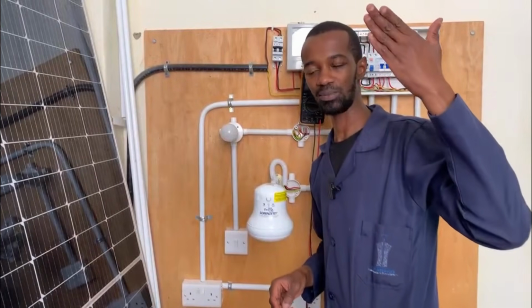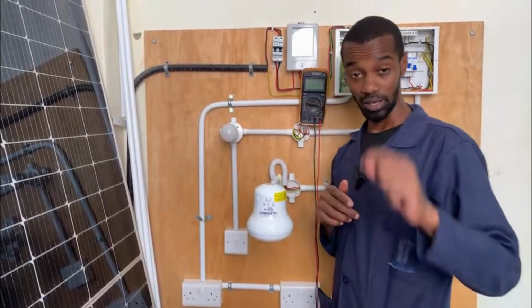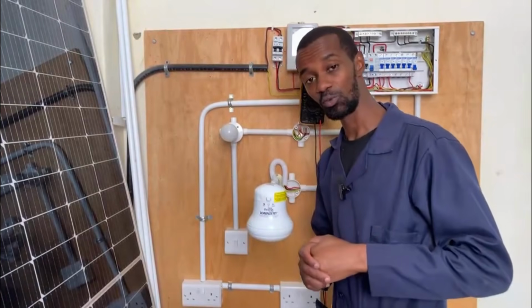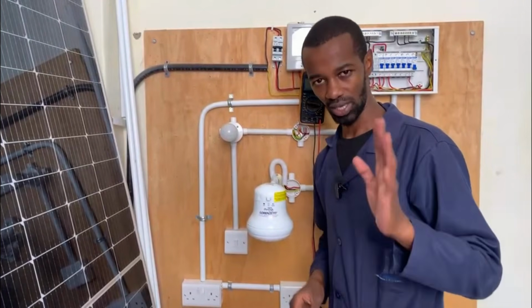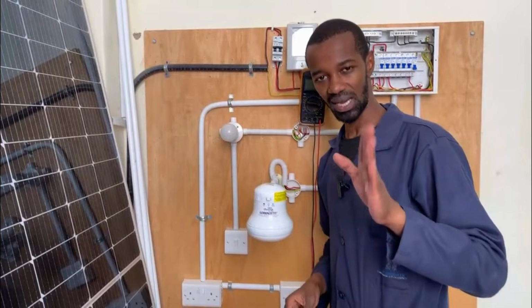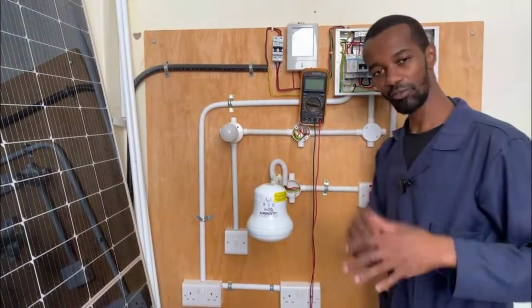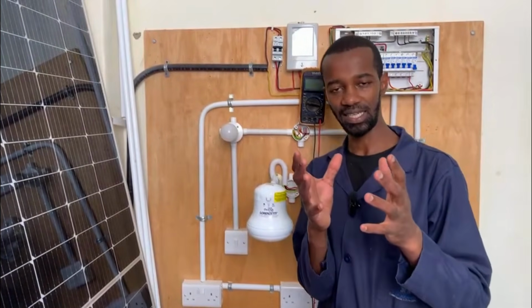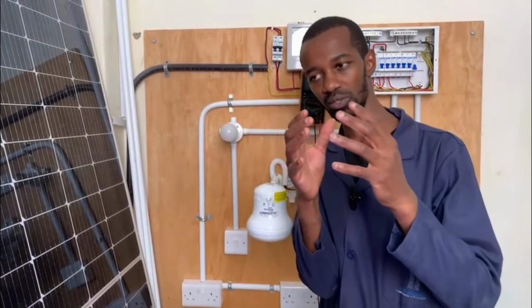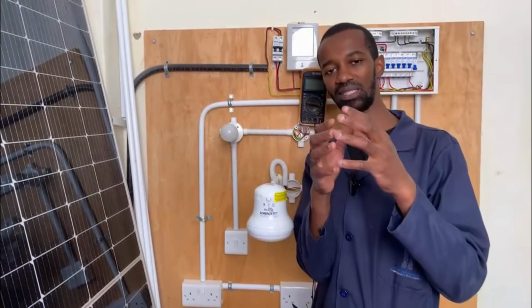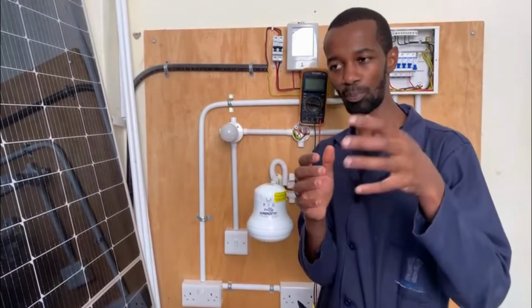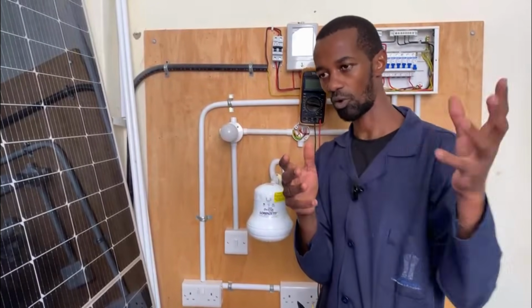Assuming your digital multimeter has a 20 like mine, if you want to record DC, which is 12 volts, you don't place it at exactly 12 volts. You place it at 20 volts, so that if you get anything above 12 volts, your digital multimeter is not damaged. You're not using the digital multimeter for that day's purpose only. You require it for more days.